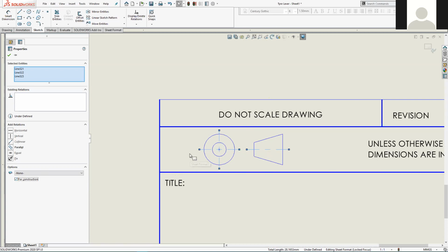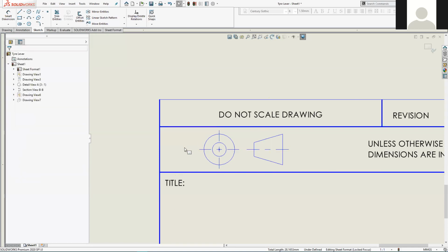So that tells the system, if we were in a sketch that we were going to create a feature from, these would be regarded as not solid geometry. They would just be there either for our reference as the user or to hold another piece of solid geometry in place. But they work for this purpose as well. So we'll click on OK.